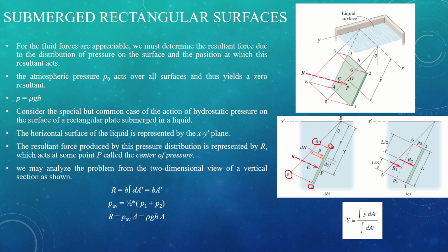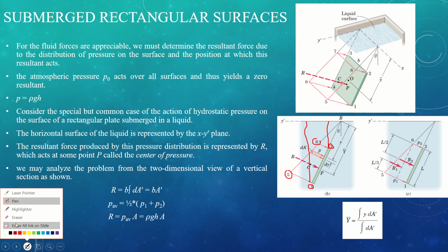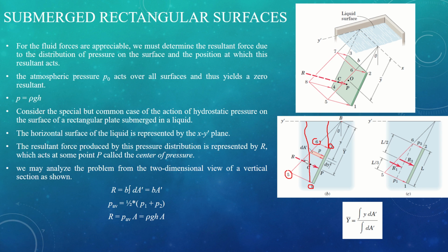Now, what is the magnitude of these arrows? Simple, rho g h. You have got the density of water, you got the gravitational field you're working in, and you got the depth. That is how much deep you're going, right straight down. You don't need much, straight down. It will give you the magnitude. This much pressure is acting on 2, and if you take further down, it has to be a straight line. At 1, you'll get the magnitude of the force acting on point 1 based on simple laws of pressure.